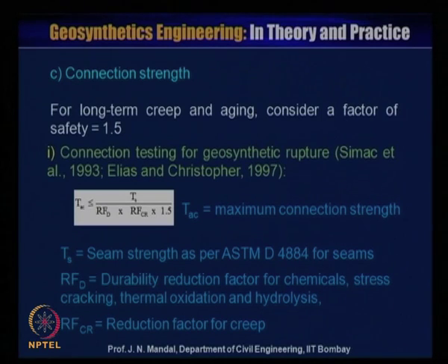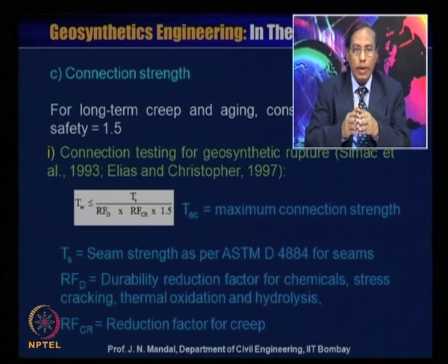Now, see connection strength. For long-term creep and aging, consider a factor of safety equal to 1.5. For connection testing for geosynthetic rupture, Simac et al. 1993 and Elias and Christopher 1997 give this equation: TAC, that means the maximum connection strength, should be less than or equal to TS, that means the seam strength as per ASTM D4884 for seam testing.